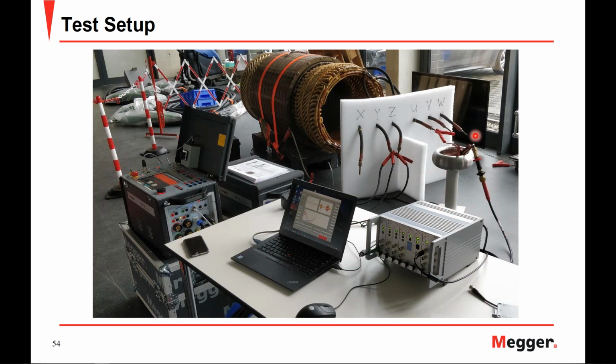You can see your high voltage source applied to your U phase, decoupling the partial discharge activity. Your measurement impedance is at the base again. Your untested phases are grounded, and then your ICM system or your partial discharge detector unit, and then your control software. So this is an example of what a test setup would look like when completed.